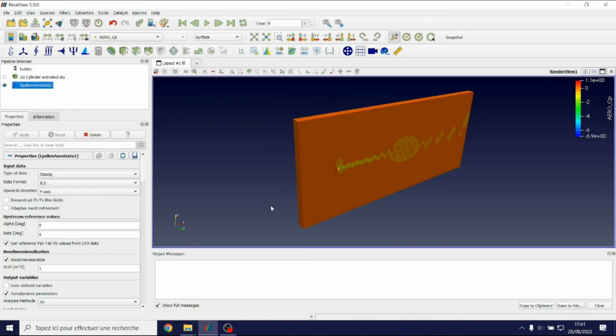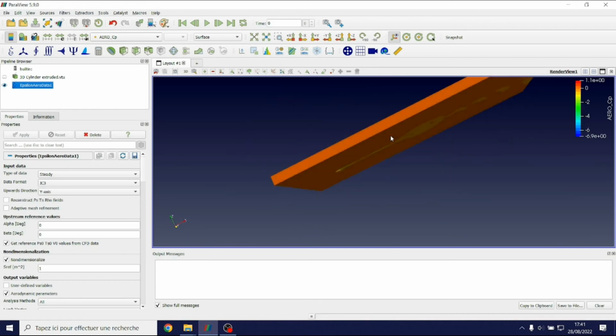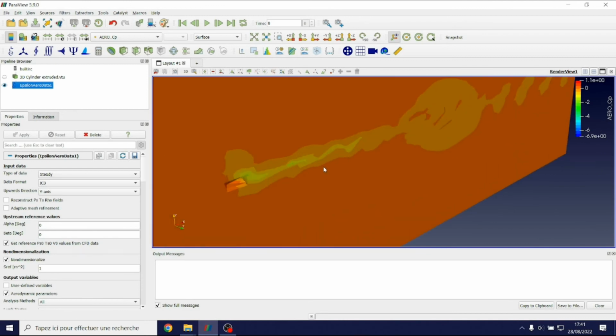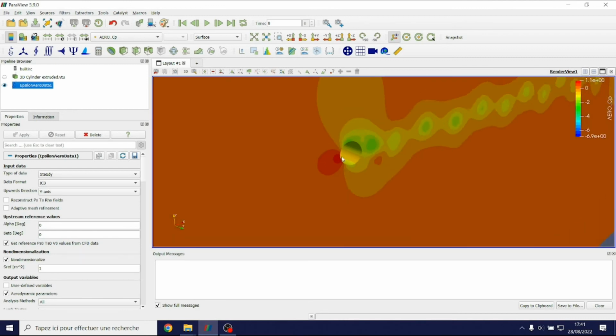This is the third case that I have prepared and corresponds to the 3D domain that has been extruded several cells along the width. This is not open data that you will find on our website, but however, I will use this case to show you two separate features. The first thing that I want to show you corresponds to the internal surfaces that appear when you solve a solution with multiple processors. You can see that very easily with ParaView. The outside seems to be nothing special, you can see actually a cylinder right inside.